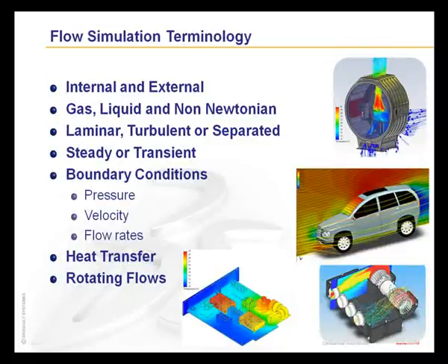We discussed the various terminology used in flow simulation and some of the steps to success that a user should consider when setting up their model. Is the flow internal or external? Is it steady state or transitory? Is heat transfer important? And so on.